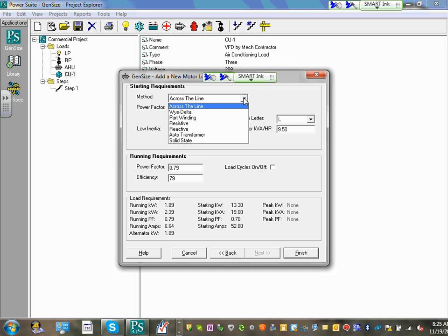Now, Adam, when you have motors, you guys, I know you did it. I know Karen, you did it. Who else? When you guys were in the motor lab, do you remember that Y delta? When you wire a motor Y, reduce the inrush, and then you flip it into delta to reduce the starting current. Or you can have part windings. You put part windings, you energize the first set, then the second set, so reduce the starting. All these are ways of reducing the starting current.